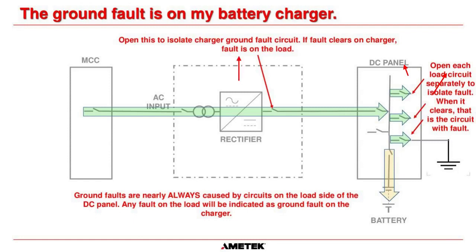So if you are in a situation where you have a ground fault on your system and you don't know where it's coming from, the first thing I always recommend our clients to do is open the rectifier output breaker, the charger output breaker here. Obviously you still need to make sure that your battery is connected.